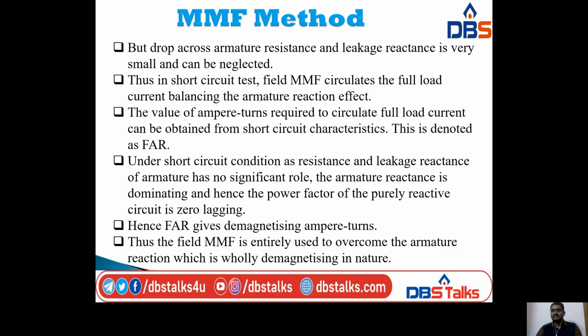So in the short circuit test, field MMF circulates the full load current, for balancing the armature reaction effect. The value of ampere turns required to circulate the full load current can be obtained from the short circuit characteristics. This is denoted as FAR, F suffix AR, because in this case I am taking the armature reaction effect. That means we have to measure the full load current, that is, I am taking ampere turns, FAR.